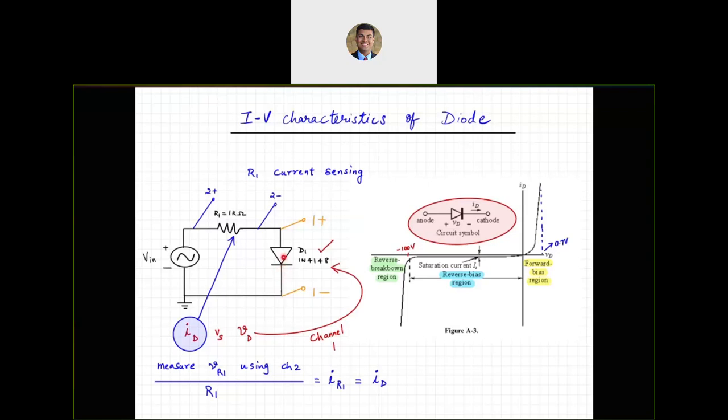Obviously, if you have more and more diodes over here, that is going to proportionately increase. So if there were two diodes over here, that would be 1.4 instead of 0.7. And whatever remains, because the sum of voltages in the loop should be 0. So if I'm giving 5 volts here and two diodes take up 1.4, then I will have 3.6 volts remaining for R1, which will result in 3.6 milliamps flowing through R1.